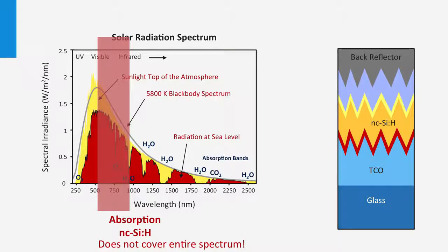Nanocrystalline silicon films are used as intrinsic absorber layer as well in a PIN solar cell. The spectral utilization of the nanocrystalline silicon PIN junction is better in reference to amorphous silicon due to the lower bandgap of the nanocrystalline silicon. However, to utilize the spectral part from 700 up to 950 nanometers, thicker films are required. Typical intrinsic film thicknesses are 1 up to 3 microns from nanocrystalline silicon.